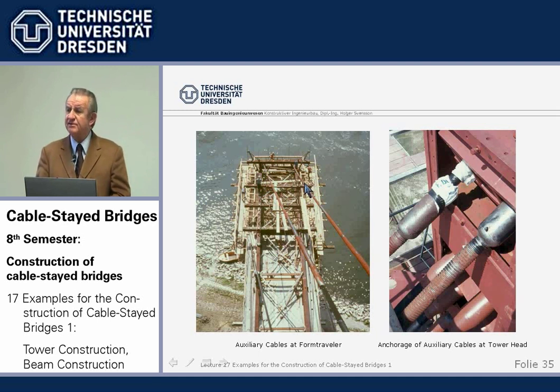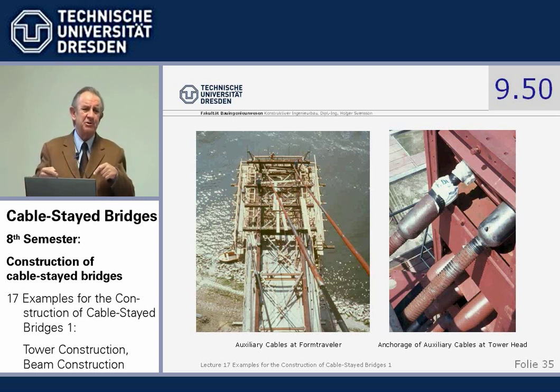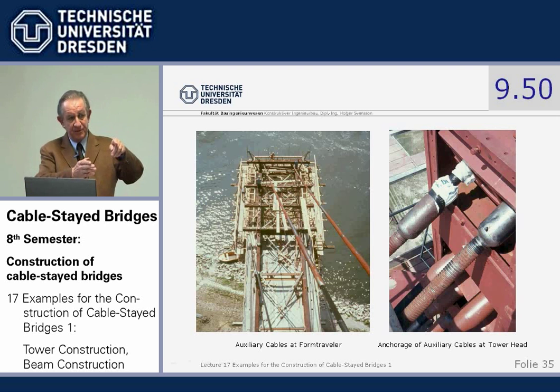Now this is quite a disadvantage, because you have to elongate these auxiliary cables for each new section, which just is time consuming. And in addition, you have to size these auxiliary cables for the biggest forces in the very last situation. So even for the very first element where we have steep cables and the force is low, we have to use cables so big that they can take up the 3 times bigger forces in the final stage. So it's time consuming and costly. And the idea of reusing auxiliary cables normally doesn't work.